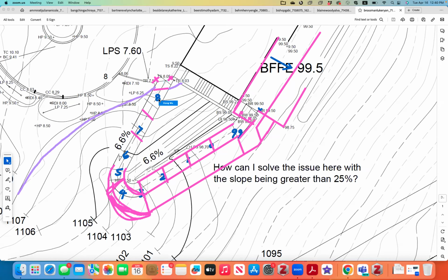Does that make sense? So that I do not unintentionally form a swale while I am doing the ramp. Make sense? Kind of. Yeah. I would turn the side slope to the other direction. And then I could connect like this. Okay, my 6 has to connect to the 6 of the ramp, and so on and so forth. Okay, so that's about the ramp.